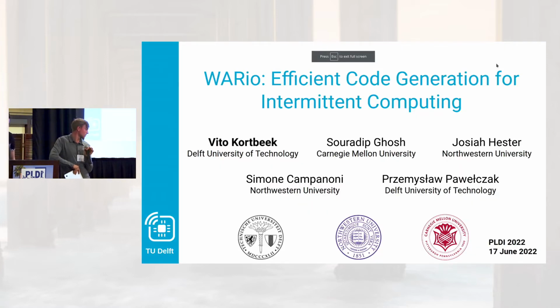And basically there was an overhead with PDL, which mostly stems from 2 things. One is our compiler is a prototype, and I know of ways to generate much better, more efficient control logic. And the other is with a really simple design like this one, there is a little bit of overhead that you're paying for abstraction, for generality, right? Which you probably wouldn't see if you're using a much more complicated system that uses register renaming, that's really using the full power of the abstraction, and the difference between a handwritten design and the abstracted design is very small. But even still, the overhead would have been dominated by just cache area. So it's not a huge overhead anyway.